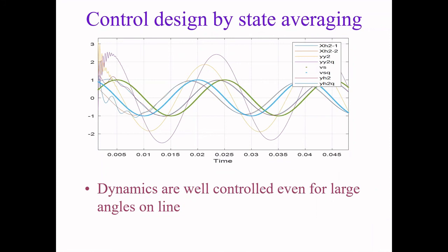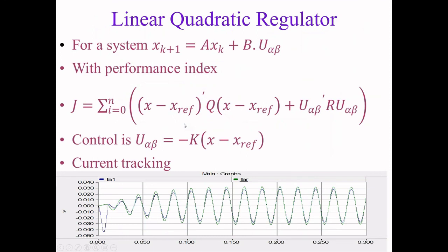And here's an example where we can see different frequencies of background oscillations between the converters, but they're well suppressed by doing our state space averaging designs, so that we can come up with solutions. And the solutions can take care of the oscillations even without knowing about them. Now, PSCAD is a very popular process of doing detailed switch modeling of inverters. So the process that I'm recommending is, step one, do the switch average model to describe the dynamics, and then simulate it with the full details to validate the performance.